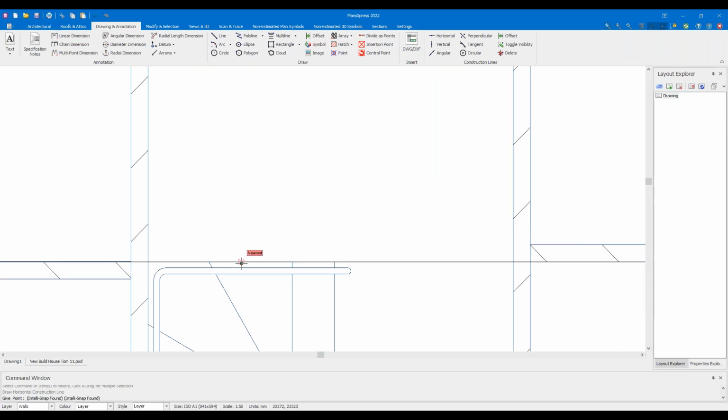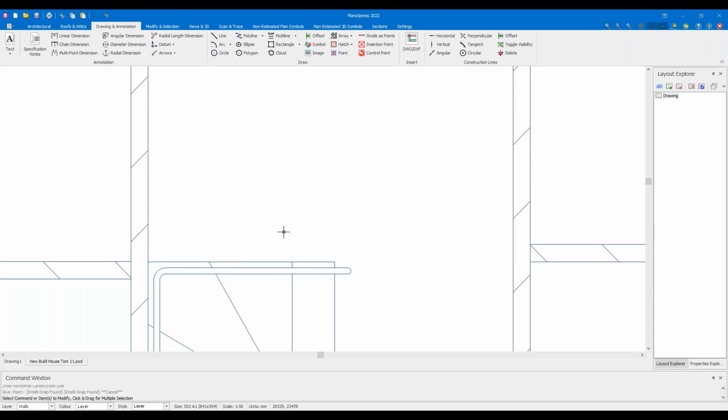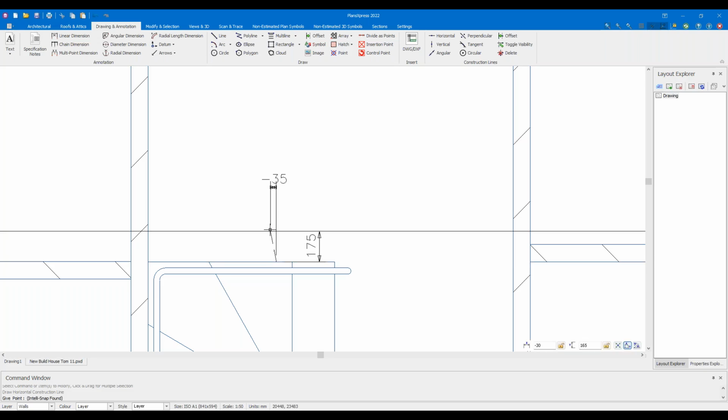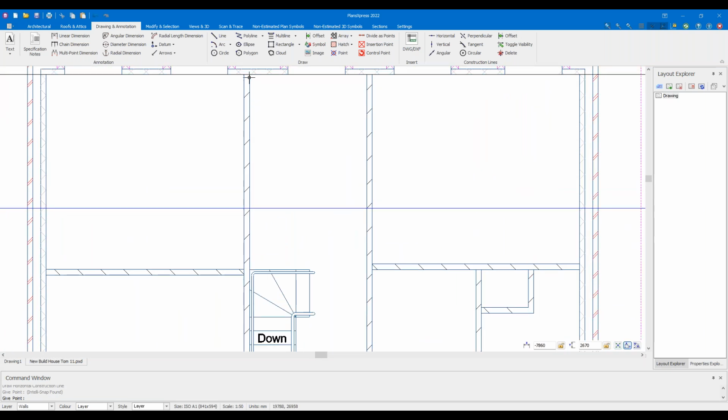I'm going to hover it on the edge of that one and press the R key. I'm going to press the distance up. Now, if I needed like a 900 wide door or more, then I need to make sure that I've got at least over a meter, because I need to also account for the 100 mil of the banister. So I could say, press the R key to go up, R key, up arrow, 1100. If I click OK, that's giving me a smaller bath from there. I could move it down a little bit. We'll see how we go with the doors.